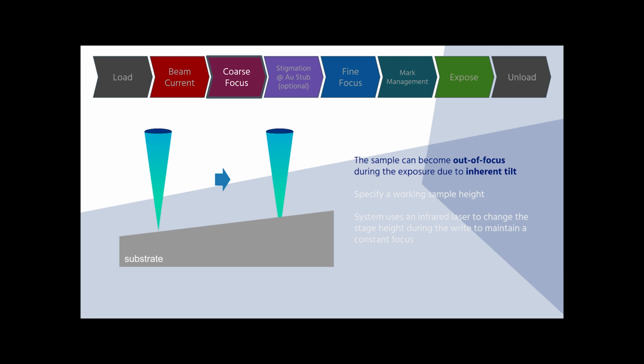Your first impulse will probably be to focus on your sample, but you don't want to start with that just yet. In an imaging SEM, you can navigate to a feature of interest, change the focus, and then collect your image. In an EBL system, if you unblank the beam so that you can check your focus, you will expose the sample in that region. You need to set the focus in an area away from your exposure zone.